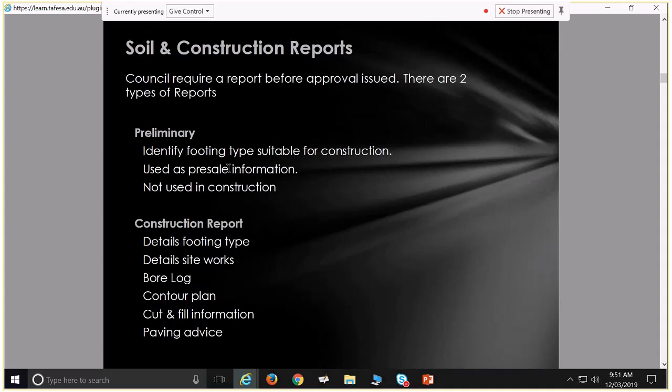A really good source of moisture typically is broken down pipes. So you have down pipes for the building taking water from the gutters. It's important that they're maintained well, and if you get down pipes breaking, that is rectified very quickly. Particularly if you're on a sandy site, you can have a down pipe pouring into the sand next to your building, lubricating all those sand particles, getting them to fit close together, and removing the support for your building.